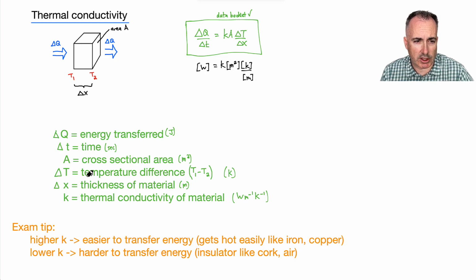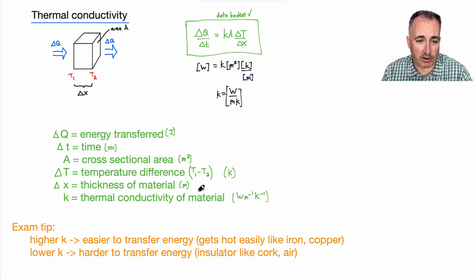So if I'm trying to get the units for K, it would be in watts, yes. And then this meters squared per meter, do you notice, will cancel out, and you'll just get a meter here. So it'll be watt, and then the meter will come on the bottom, so I'll say over meter and Kelvin. That means the units will be watts per meter per Kelvin. That's why the units for thermal conductivity are watts per meter per Kelvin. So this is just an analysis of the units.